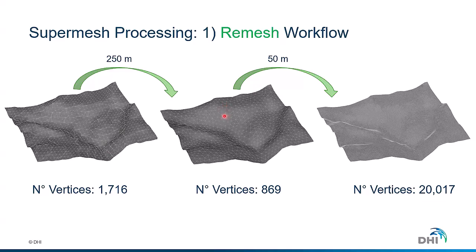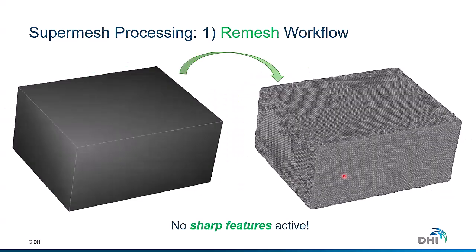If you suggest a sharp angle of typically 120 degrees, then we can end up with very regular meshes. So in the extreme case, if you have a cube or a box, and you remesh it without these sharp features of the sharp angle, then your borders could also be a little bit distorted by the remeshing process. But it's worth saying that this is basically not a proper surface definition. So normally you will need to have this information split.